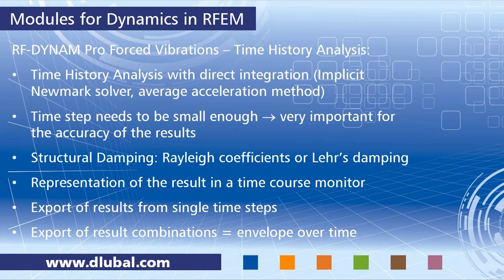about structural dynamics. Very important for the Newmark solver is to have a small time step. It needs to be small enough to get accurate results. I will come back to this point later on, and I will give some recommendations for the time step. We have the structural damping implemented, so you can choose between the Rayleigh coefficients and the Lehr's damping, and you can enter them vice versa. This is converted internally, so you can choose whatever you prefer.